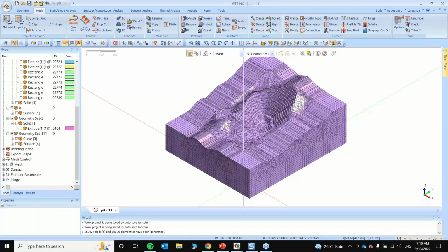A lot of people have doubts that the values that we are getting from the slope stability analysis are very high. The values will be high because at those threshold values the slope will fail. The slope will not fail at a lower displacement value or a lower stress value. So that is something you have to take a look at.